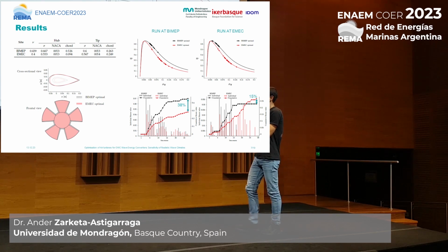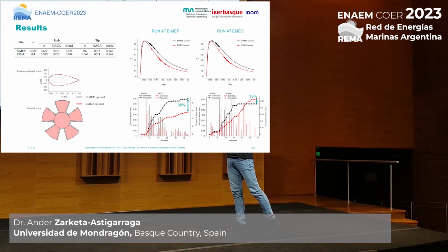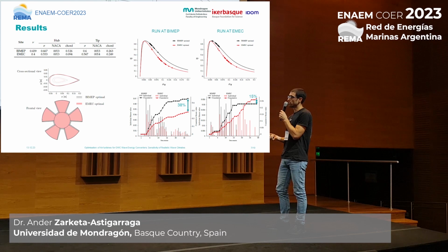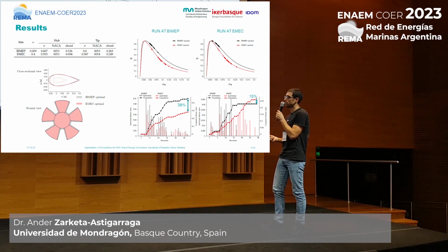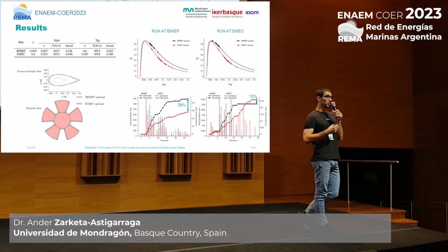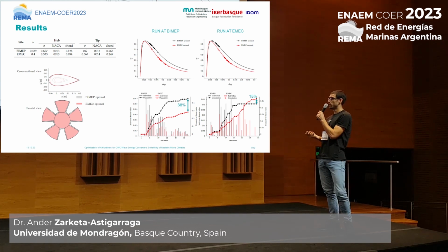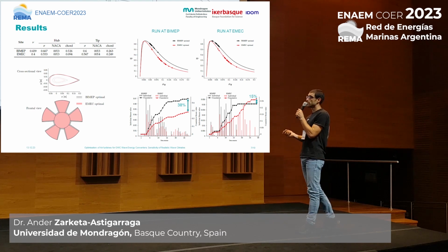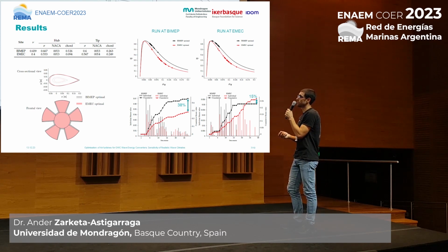Now, what it seems is that the IMEC optimal configuration is asking for a lower height-to-tip ratio and lower variations of the chordal distribution along the radial direction, which means that the IMEC optimal turbine is somehow asking for lower blockages of the pipe. Okay? Besides, it seems that the NACA distributions are not playing as relevant a role as the height-to-tip ratio and the solidities.